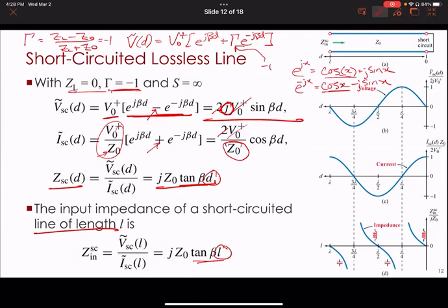Okay, D, because it can be a little confusing. For distance from the load, we've now used Z sometimes, we've used D sometimes, and sometimes we use L. What I'm saying is they're all kind of the same thing. There are slight distinctions. Z and D are just the same, there's just a negative sign. L is just us saying the entire line is L long, so it's like D equals L to get back to the input. But all of it is really just starting at the load, how far away am I going down the line?